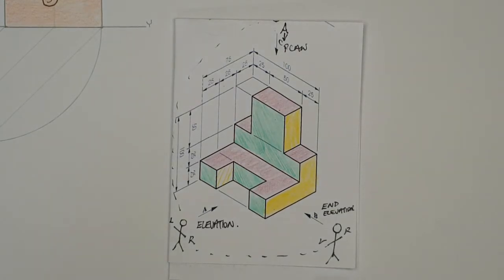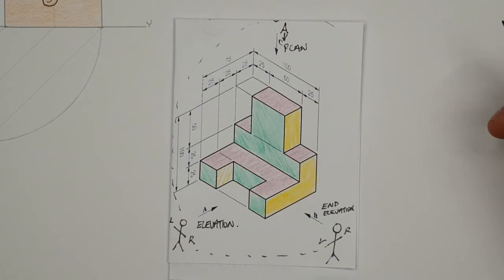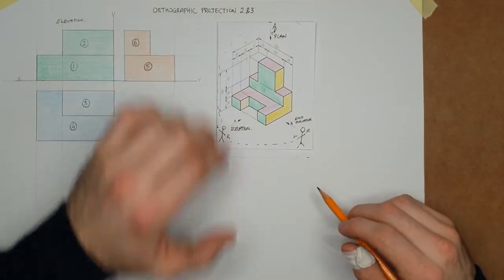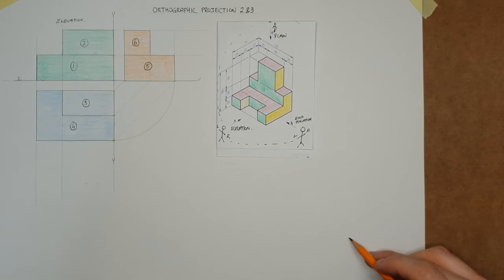A little sketch to plan out my views would be very handy, just to make sure we're not going to make any mistake. The arrow A looks in from the left, so the view is projected to the right. I'll zoom out so that I can put this on paper, and sketch it down here in the corner so that we can see what's happening.